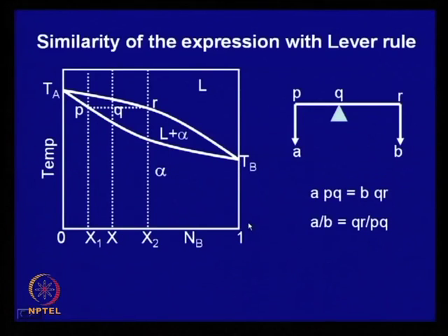So, that is why this rule in phase transformation is often known as the lever rule, and we will apply this to any of these phase transformation processes wherever the transition takes place from one phase to another over a temperature range. This helps you to find out the amount or percentage of transformation or the amount of a particular phase at any temperature.